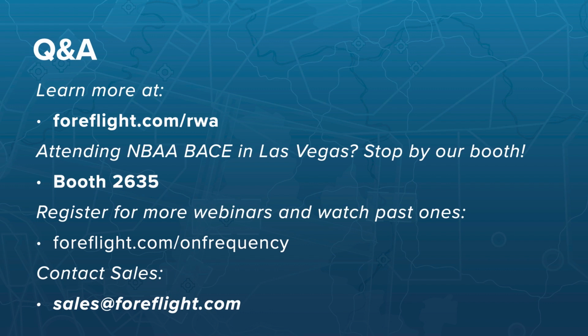I think from a usability standpoint, it's quite nice to be able to be on the ground with ForeFlight Mobile, at the office, at FBO, etc., and be able to compare the EOP that you've selected for your runway analysis with the departure procedure that you're most likely to receive in your ATC clearance. So it's really handy to be able to have graphics and text to compare the same EOP and get an understanding for what each one entails.